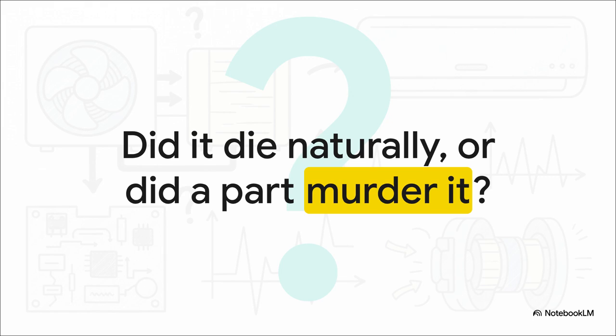Always do your checks, test your hertz, verify your voltages, and ohm meter your windings before you just start swapping parts.